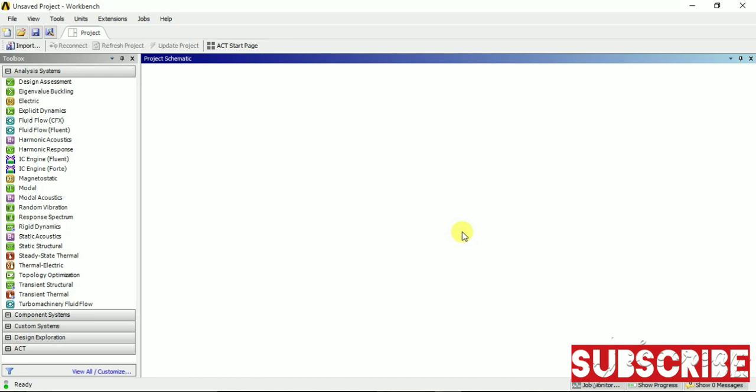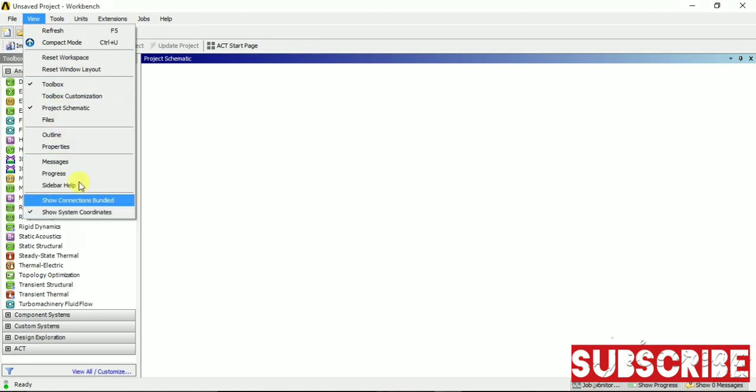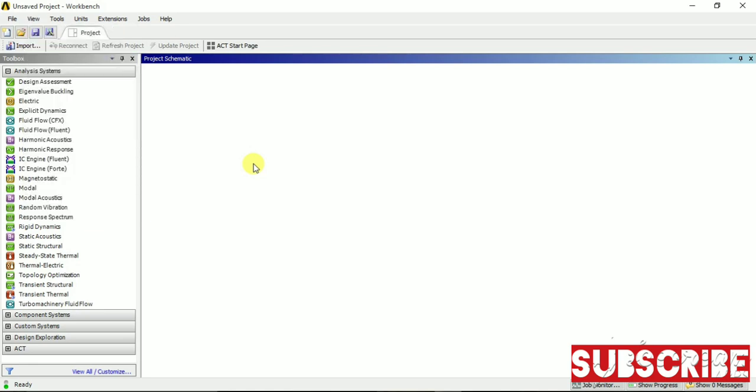Okay, now when we double click the ANSYS Workbench icon on the desktop, a window like this will appear. It will be an unsaved project of Workbench. The first thing is that you have to set the view as default so that your toolbox, project schematic and system coordinates are visible to you.